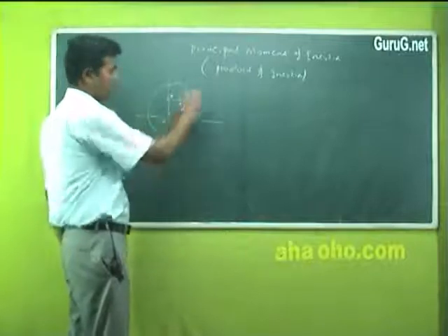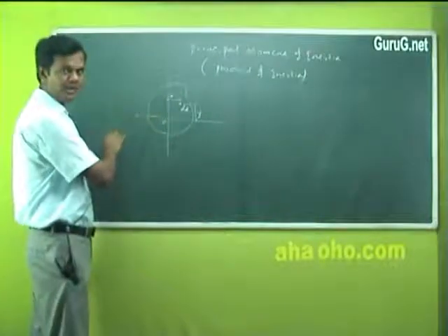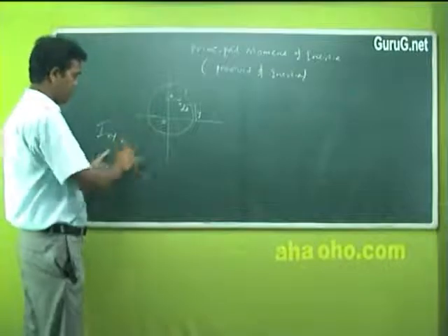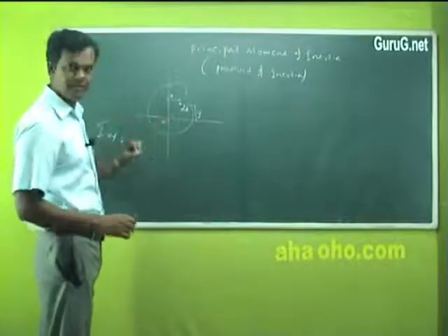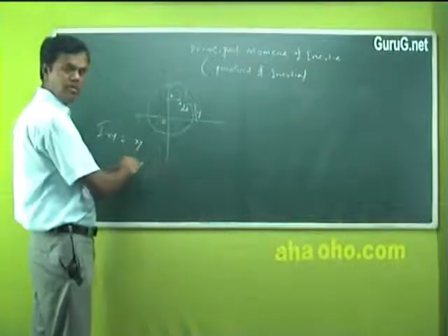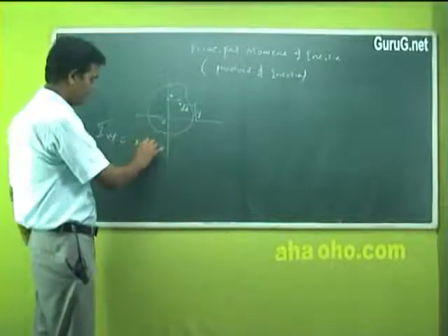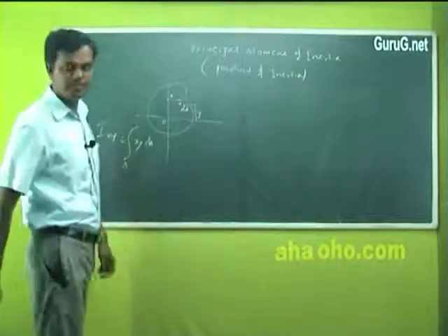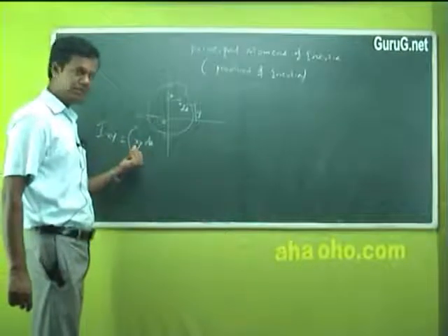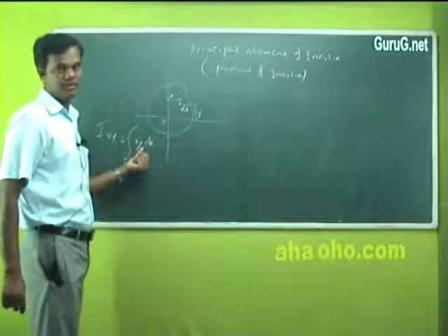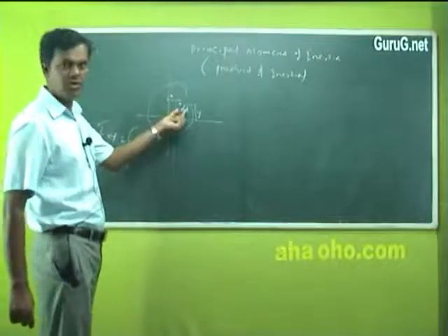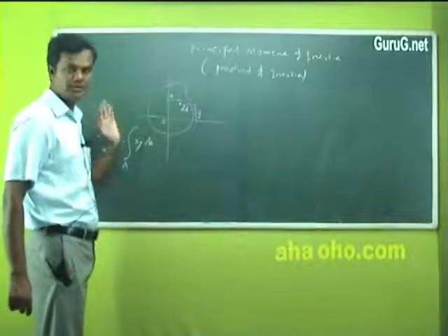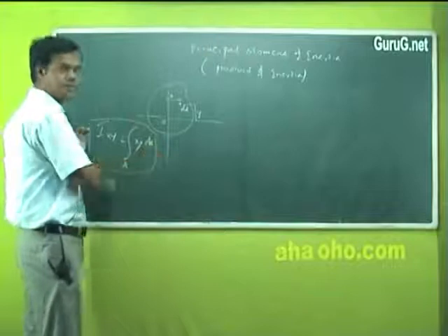So here in product of inertia we are going to multiply the values of your x and y, Ixy, which means we are considering the elemental length, a small xy value of these coordinates, and we again integrate with respect to the total area. Product means the coordinate of x multiplied by the coordinate of y. That's the meaning here. So here the elemental length will normally be a very small value, and finally we integrate with respect to the total area A for any body which is considered. So finally we'll get the product of inertia values.